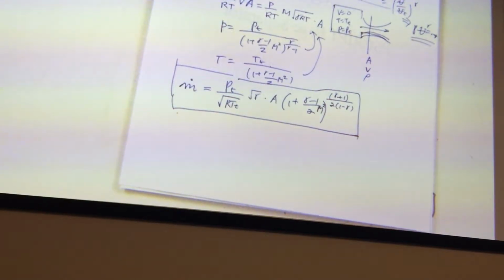Okay, now, here something is important because this all comes from isentropic flows. So that, again, the PT and TT will be constant throughout the whole flow field. And then PT and TT is what is in the reservoir. And the reason I mentioned supersonic wind tunnel is that they're using the reservoir to drive this supersonic wind tunnel. So the thing about a supersonic wind tunnel is really something similar to this. So it's all the same. It's just that in a rocket, you just chop the other parts off and just let it go out, right?